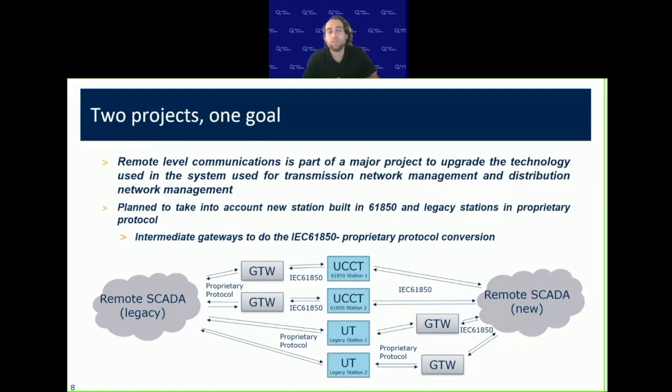Once the new system comes, then those new stations that have been migrated to 61850 will be able to talk directly to that remote SCADA, and we will use remote protocol conversion gateways in order to do the translation between that proprietary protocol and 61850. And as we migrate the different stations, we'll migrate all to 61850 until one day we should be able to be 100% 61850 in all stations.